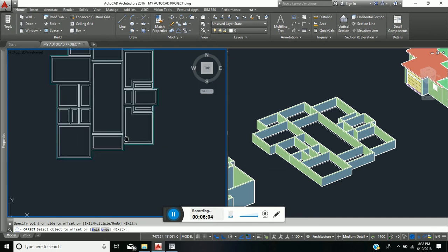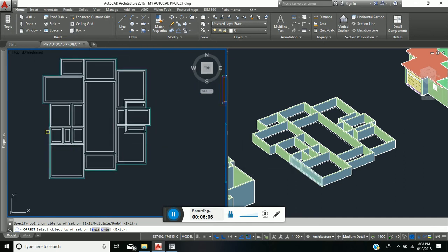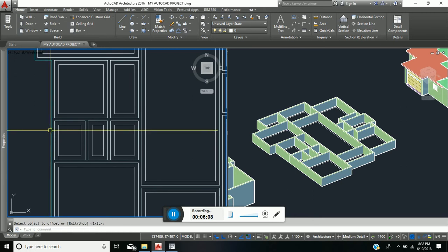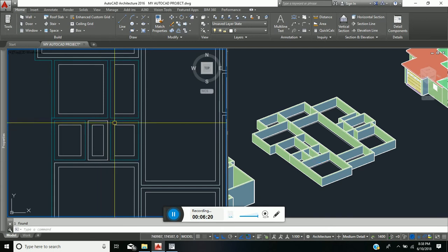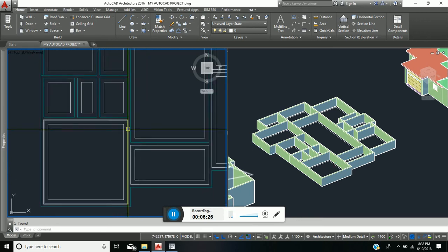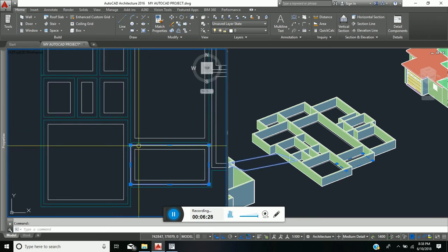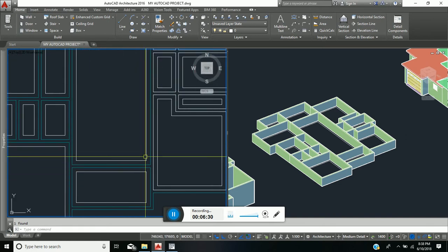That was pretty quick. Alright, now what we want to do is to basically delete or remove the ones we had put on our walls. We had only put them, like I said, so as to have something to offset from. And so now I'm selecting and removing just the ones on the walls. I'm not removing the ones we have offsetted, just the ones we have offsetted from.